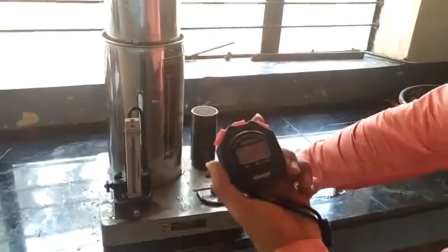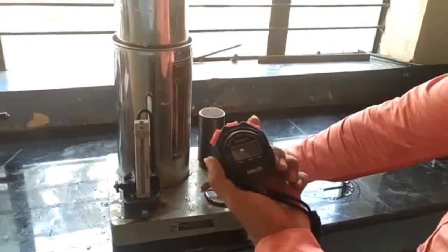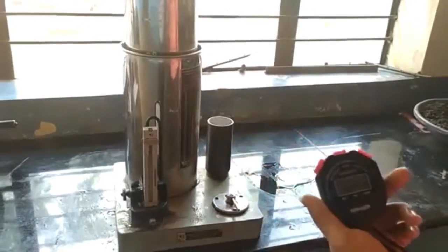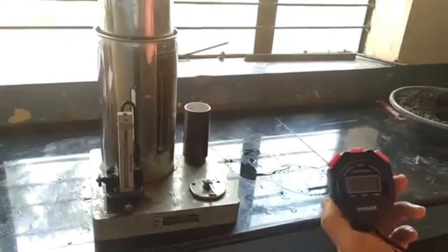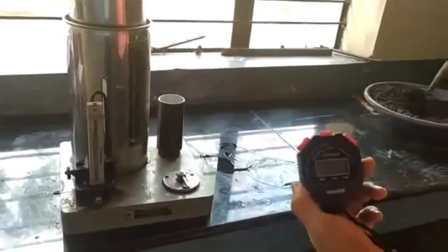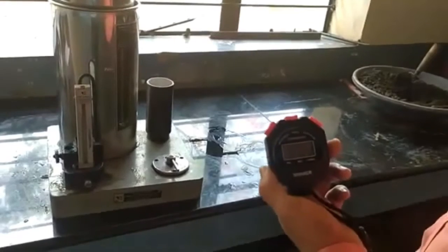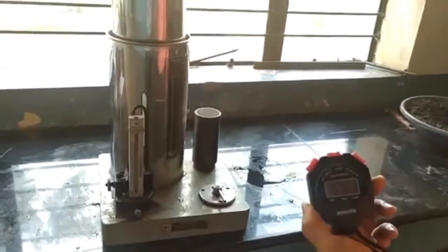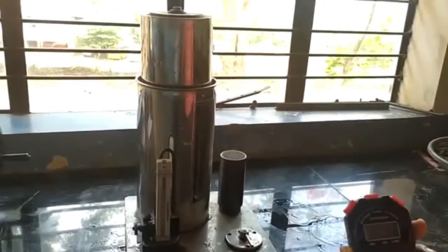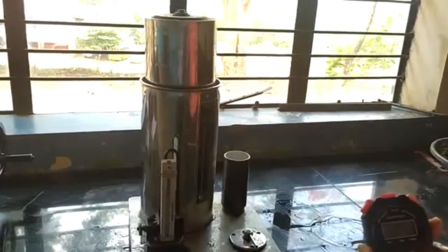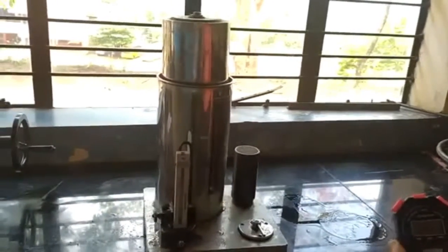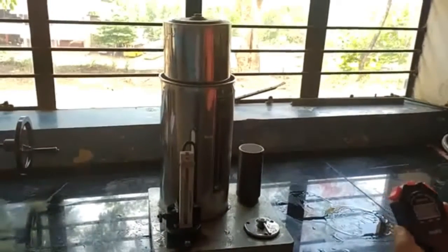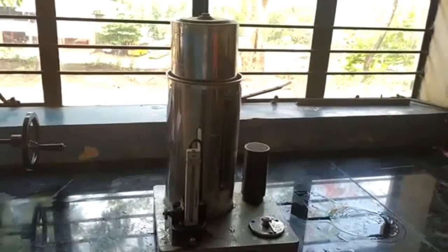Now move the valve position from open to pressure P and simultaneously start the stopwatch, to note down the time in minutes to pass 2000 cc of air into the specimen through the orifice, and you can see the air tank slowly coming downwards